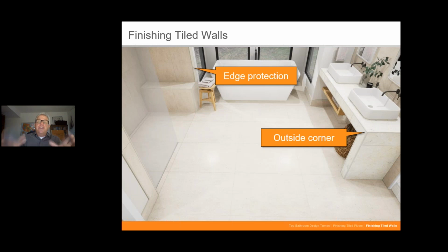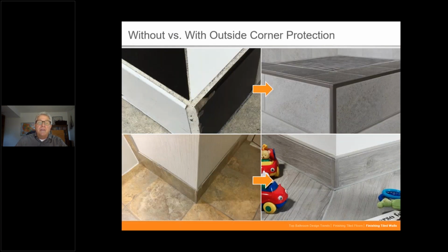In other words, just the tile with the abrupt edge around it, and not necessarily the glazing or the coloring going clear throughout and covering the edge. So you don't really want that to show. Plus you need edge protection, and you want it to look like a very professional and clean application. So you can see a couple places we've called out here.